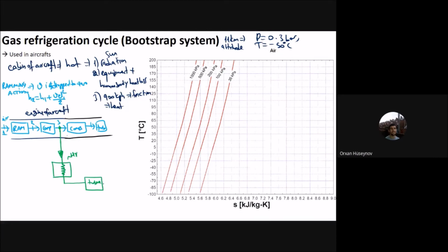So this turbine outlet is sent to the cabin. It is at a lower temperature, and this lower temperature T low is sent to the cabin, and it cools the cabin. Okay, this one is for the passenger cabin. And you can see this is the turbine, and this turbine generates some power. So this power of the turbine goes to the shaft here.